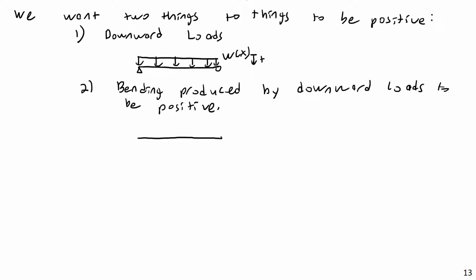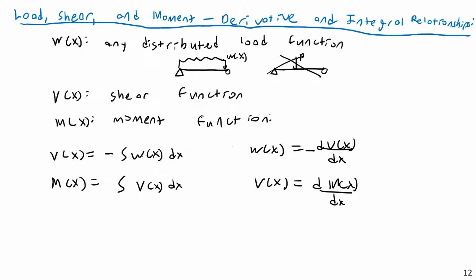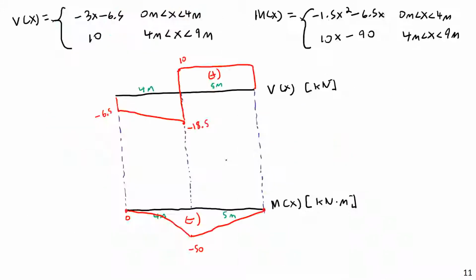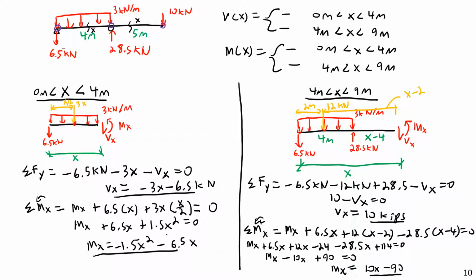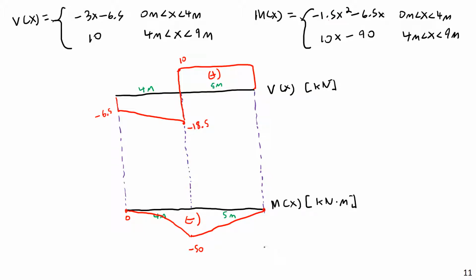So in other words, if we have our same distributed load there, maybe I'll just show a point load for simplicity. If we have a downward load, we want to define this type of bending as positive bending. Again, just because that's the type of bending you encounter in the field and in real design cases a lot more than upward bending, although you certainly do have those sometimes. In fact, our beam here, with its negative bending moment, is one where you would have that, from the previous lecture. If you were to draw out the deflected shape, this is the original shape here. Its deflected shape would end up being something like this, concave down throughout.